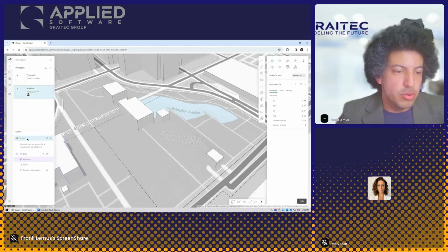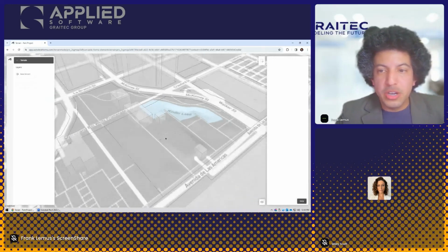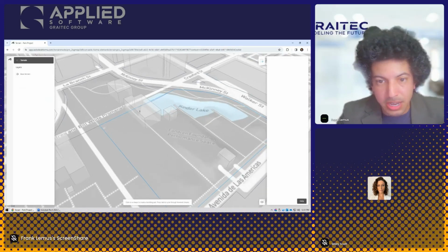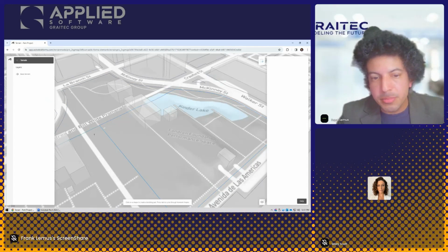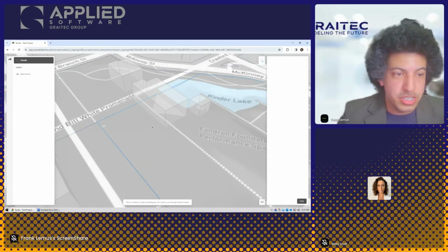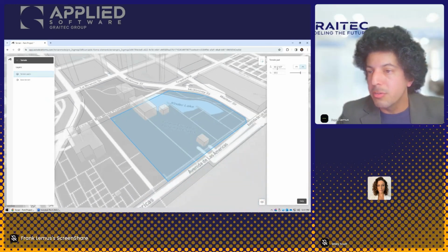Now, actually, notice you have the terrain, and terrain is available outside of the base, okay? Which means that I can come over here and I can say things like terrain mode, which will allow me to go in here and select different shapes. And you're going to see how we can create extra custom shapes because you may not want to modify this entire property line area. You might just want to modify a tiny little place down here. Let me show you how to do that in just a second. But the idea is that when you select an object in this mode, then you can come over here and make adjustments to it. Okay.